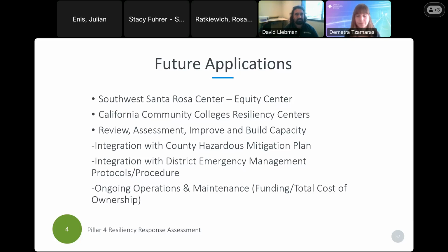So air tightness, looking at replacing windows, insulation, and then lastly, looking at new phase change material that really gives us the ability to have thermal energy storage in a passive way. We see this as a really important technology in allowing our buildings to thermally flywheel, as is one terminology I've heard, when we need a load shed. And so we could focus first on turning off the heating and cooling systems and having built-in capacity in our buildings for folks to be comfortable.